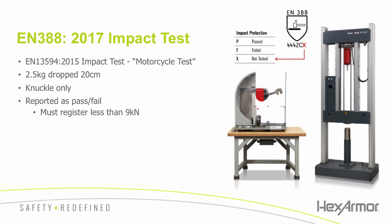So in the EN 388 test, the glove is cut in half, so only the material on the top of the hand is being tested. And then there's a 2.5 kilogram striker that's dropped 20 centimeters, which is roughly 5.5 pounds dropping 8 inches, to strike the glove material.